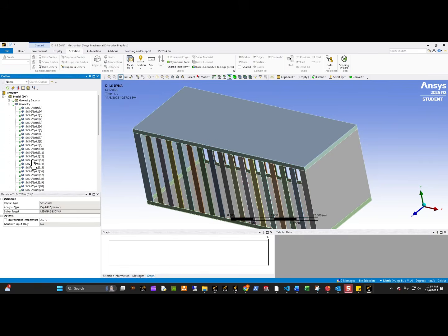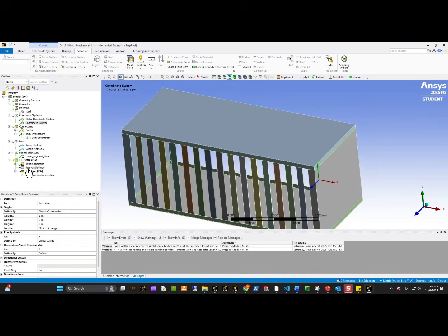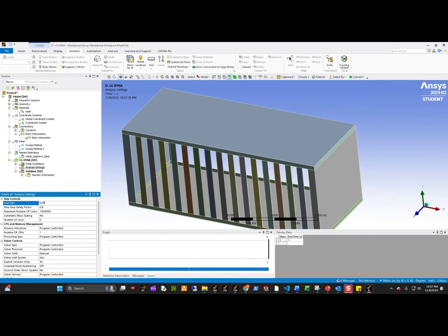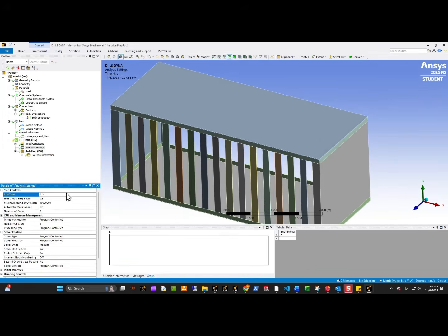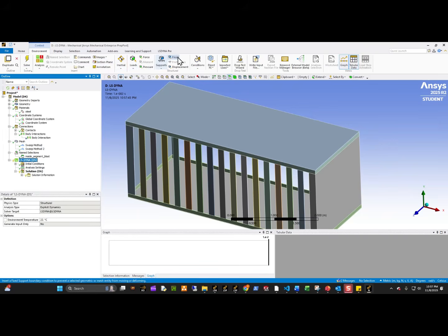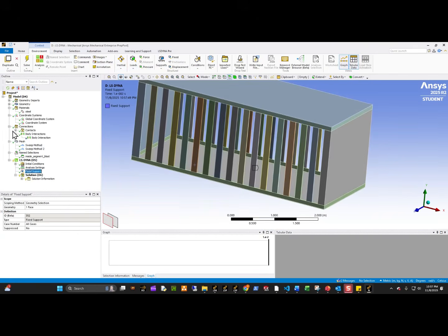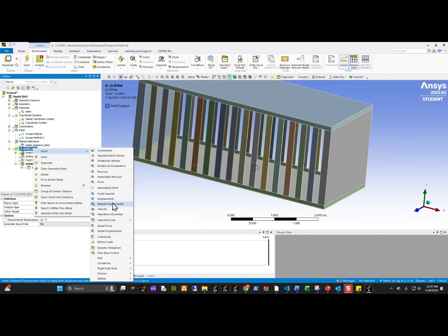Okay. Now remember, my blast source is located where I created the coordinate system, which is at 200. I'm going to set the termination time to something like 0.001 or something like that. This is a really short duration. I don't have to run the analysis for too long. Maybe a little bit longer, 0.01. Okay. Let's fix the bottom surface. Fix the floor. The whole thing stays. I have my contact already selected, right? So everything's bonded together.